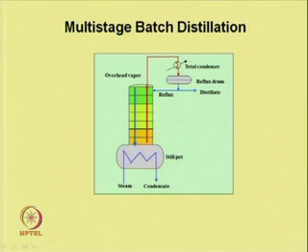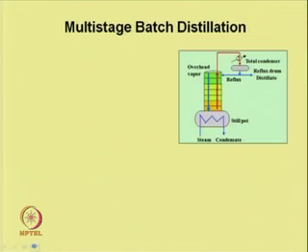As we can see, the purity of the product is governed by the concentration of the feed and the fraction distilled out, which is taken out. Whatever we want, the product purity can be achieved if we use multiple stages, and we can get purer products. Now, in this case, we will assume, similar to the fractionator, constant molar overflow.